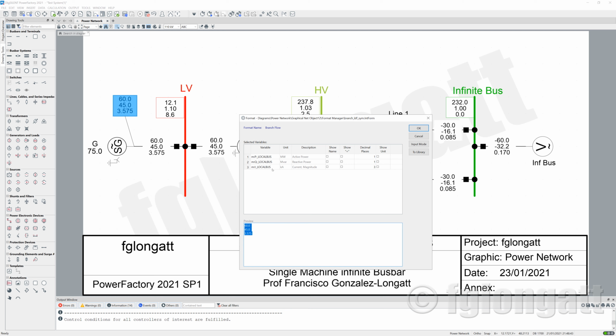Okay, I know that many of my friends are top users of PowerFactory. They will tell me, no, there are other ways to do this. To be honest, I am doing this in a very simple way, just to show my students how to do it. Okay. What I did is right button here and append a row. That is just to tell PowerFactory I want to add a row, and now I can define the kind of results that I want.